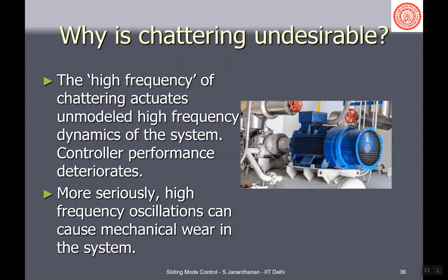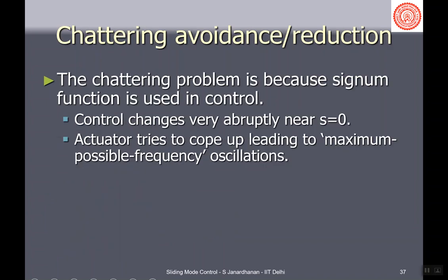You see that in areas like this there is a high frequency vibration, which is actually being amplified here. These joints over time will get worn out, and during normal operation we will not notice anything. So chattering is going to cause high frequency dynamics to be excited and cause mechanical wear.